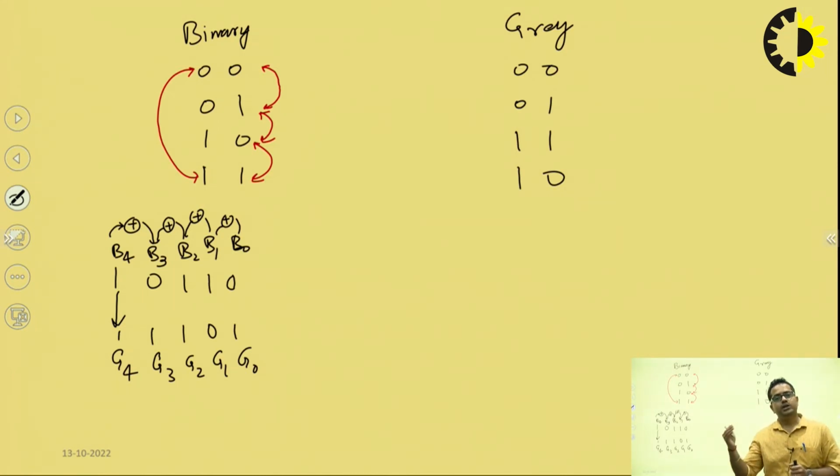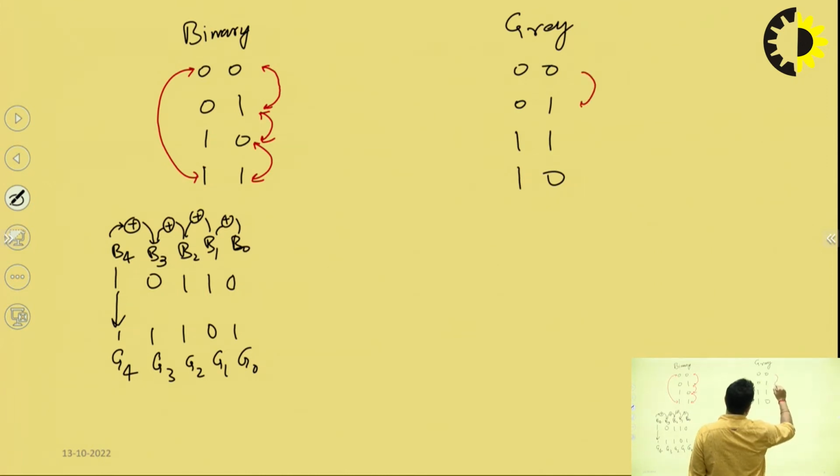Otherwise, if we use binary code in the filling of the cells, there might be some adjacent cells where we won't get a reduced form from those combinations. So in order to get the reduced form, instead of using binary, you have to use gray code.